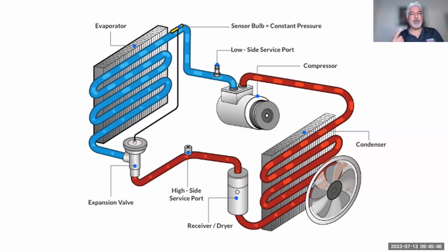So in this case, one compressor, but the regulation of flow for the evaporator in the back for the rear air was an expansion valve, while the accumulator dryer was used to protect the compressor on the front AC because it was using an orifice tube system. Therefore, the suction side return of the compressor had an accumulator in it. What I'm trying to say is you can have a combination system where you've got an orifice tube and expansion valve on a dual air system that you're going to see there. So definitely want to do that.